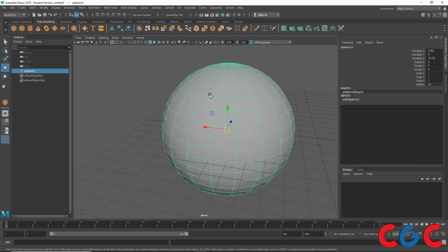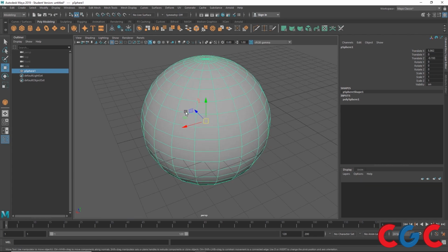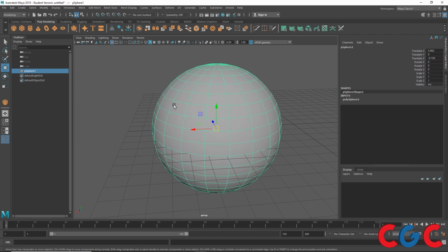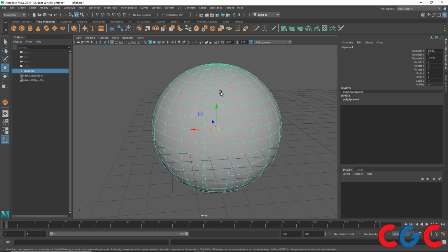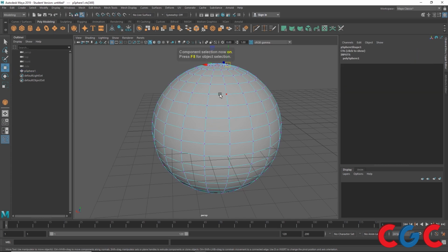Right. Here, how do we select them? We can select and manipulate them in the same way we selected the objects. But for selecting components, there are many methods. There are more options than selecting or manipulating an object. Now we select by right clicking on an object and selecting the desired component. Otherwise I can press F8. After pressing F8, I can select any component. Because of our earlier click on vertex, it is still selecting vertex.